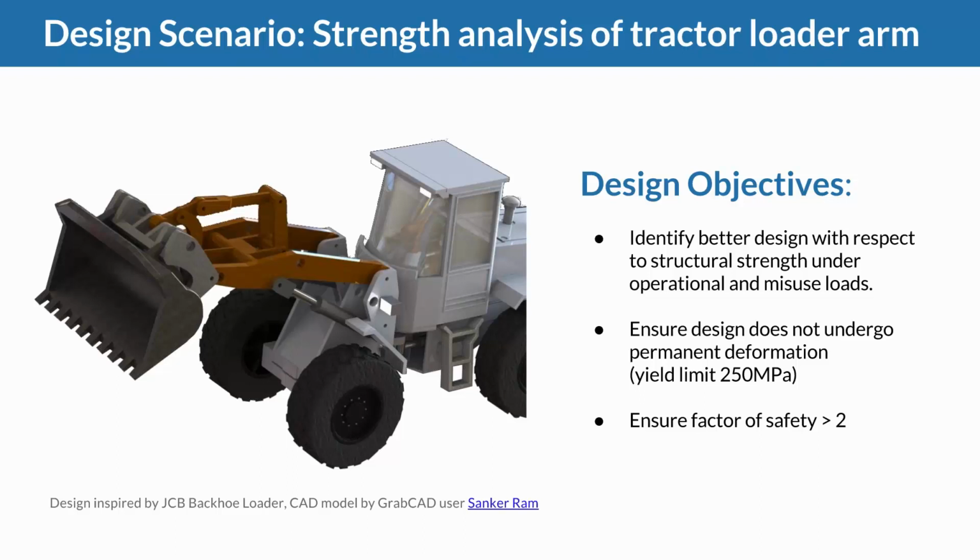But on the other hand, if our factor of safety is too high, probably we used too much material on a specific part and should be able to reduce the weight of the part and the material to save money during the build. One important factor here is also fuel consumption during operation. So maybe fuel consumption can be reduced by a few percentages if you reduce your overall weight in the same range.